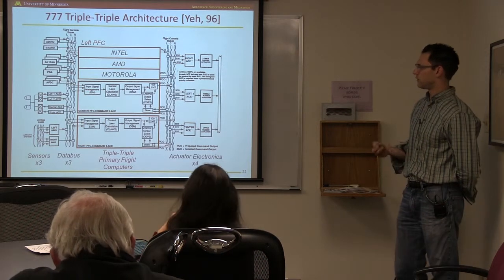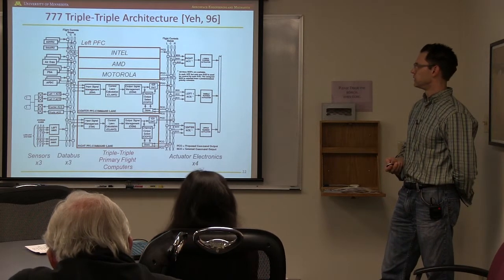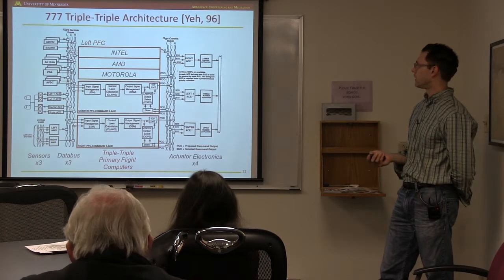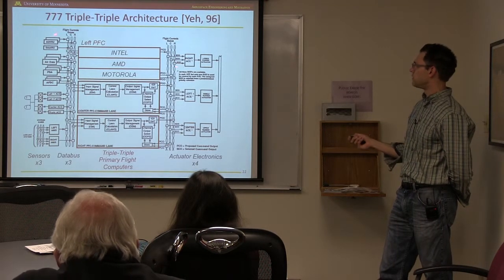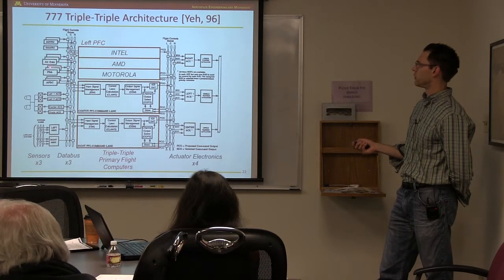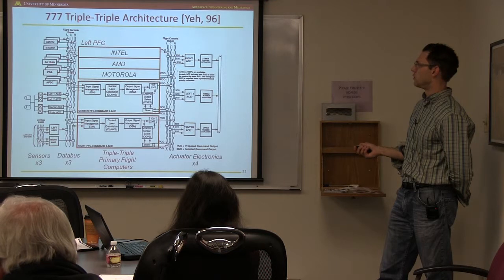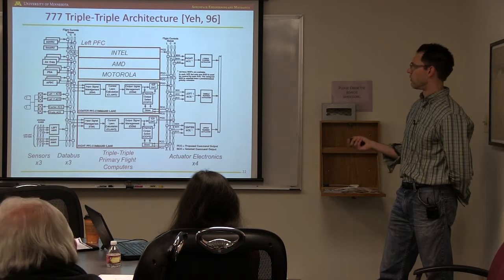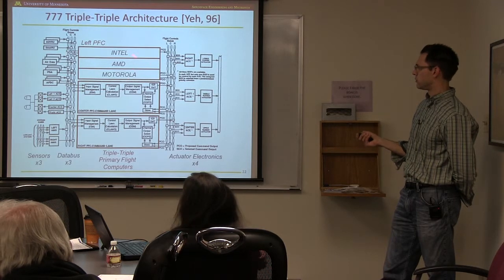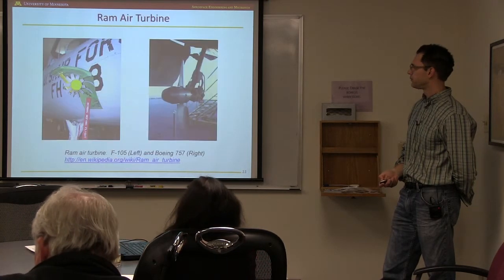And then I mentioned that there are very tight requirements on the probability of failure. So if there's a random failure, that's why you have maybe 3 different sensors, so that if one of the 3 sensors fails for some random reason, the other 2 will take over and outvote it, so to speak. So there's a notion of using dissimilar components, but then also replicating those.